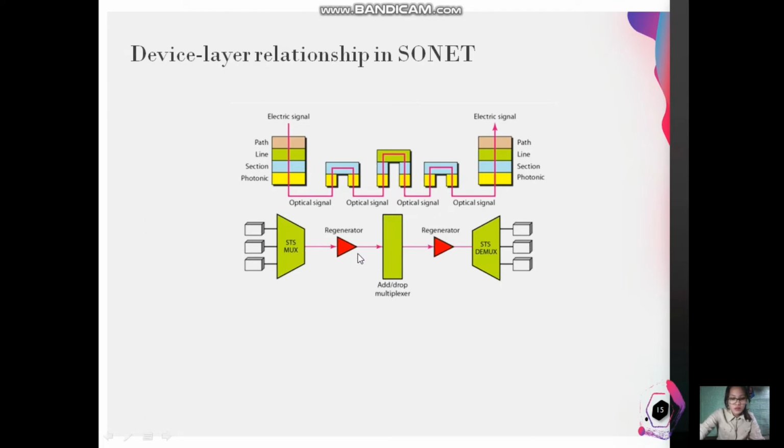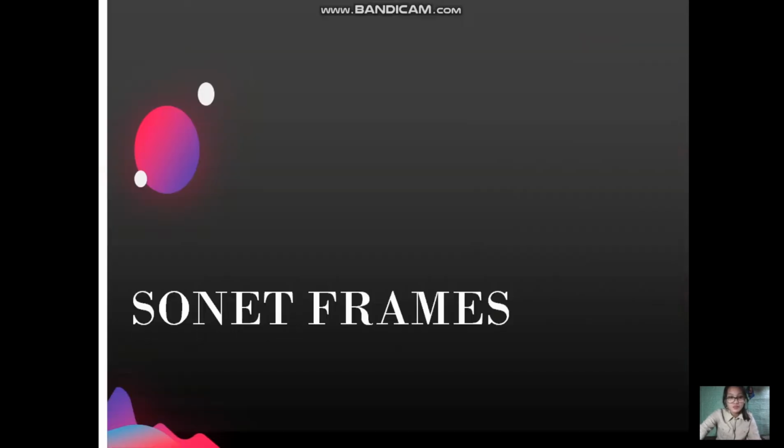Remember I mentioned earlier that the SONET designers were interested in carrying their legacy plesiochronous traffic. Because of this, they tied everything to the existing voice traffic. In the digital telephone network, voice is digitized according to ITU specification G.711. That is, the granularity of the voice samples is 1 octet, and samples are taken 8,000 times per second, or every 125 microseconds.